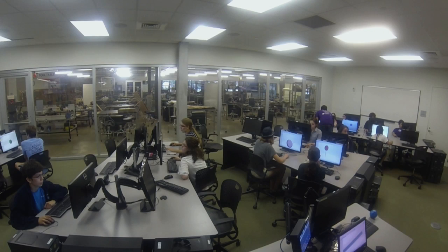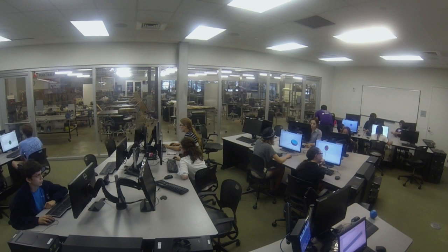If you select these two faces and hit check, it'll give you lines that go the whole length of the cylinder, basically the projection of those circles on this new sketch plane. You want to make those projections constructions, since you don't want to use them later. But they let you do very nice dimensions to them now, so you can put them wherever you want in the center. You can make a full square to get the whole dimension thing and do it the same way you would the whole time before.